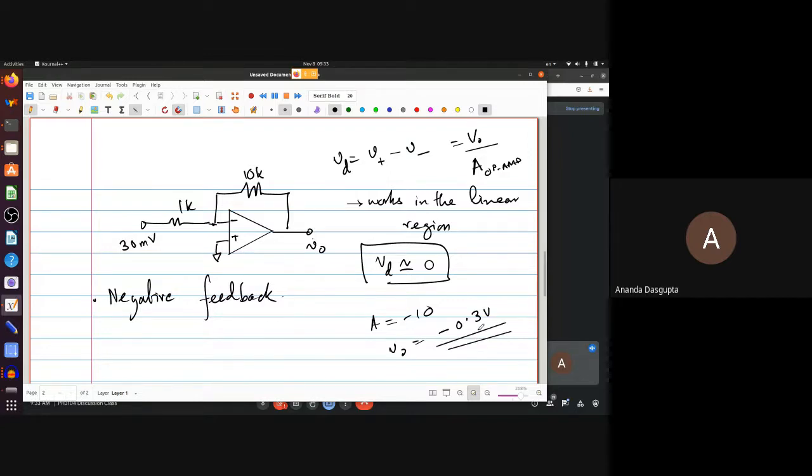But rather than rely on the formula, let us just take a look at what happens in the circuit, stage by stage. So first of all, we want to figure out how much current is flowing through the 1K. Anybody tell me that? How much current flows here? The beauty of op-amp circuits is that usually you can analyze them just on paper, by drawing a few arrows, and most of the calculation can be done in your head or on a simple calculator.